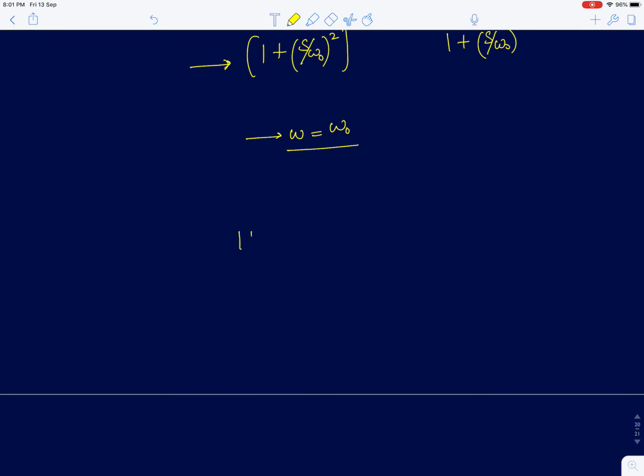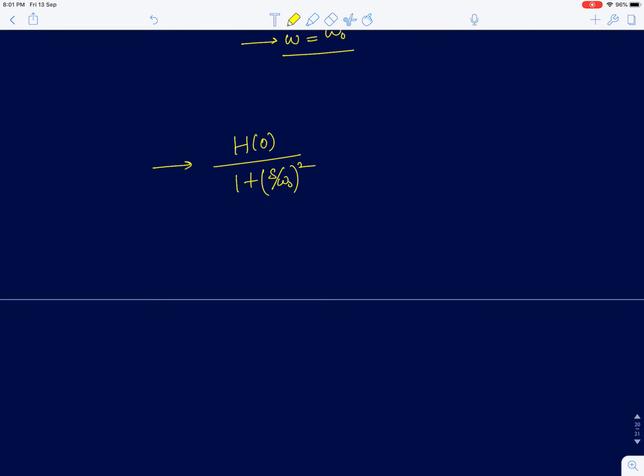So first I'll take the simplest. This is the low pass second order lossless system. I'm going to feed a sinusoid which is cos omega naught t. I've chosen cos here with an amplitude, say Vp cos omega naught t into u of t. In the previous lectures I might have chosen sine. It's a sinusoid at the end of the day. I'm just looking for a signal with an infinite gain at a single frequency.